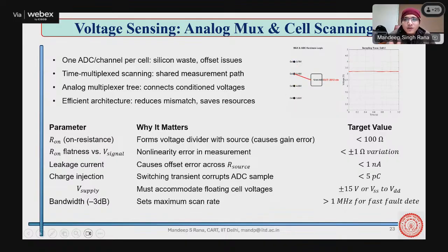Generally, we go for 8 input ICs, and there are some 12 input ICs, but they cause slow sampling of the data. If I want to read 8 data from one ADC running at 1 megahertz, it takes something like 20-25 cycles for just one data. Reading 8 data, 25 multiplied by 8, so 200 cycles are required just to read this 8 data once.